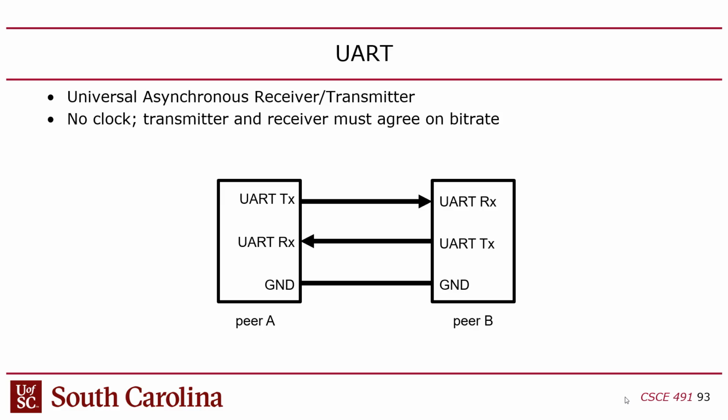Another common mistake that I make constantly is getting the baud rate wrong. The receiver is using a 9600 baud rate, and I'm using a 57,600 baud rate, and then it doesn't work. And you never know what the baud rate is. I never know what the baud rate is supposed to be. Never. Every single time I've ever connected anything to UART, I had to guess and use trial and error. Because it never tells you, it's never clear what the baud rate is supposed to be. I hate that.